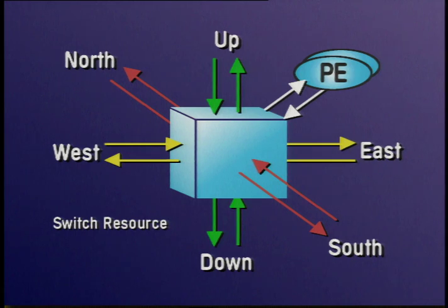Unidirectional switch and wire latency for a 2-byte wide packet per physical unit is typically 13.3 nanoseconds. When routing requires a corner turn, there is only an additional 6.7 to 13.3 nanoseconds of delay.